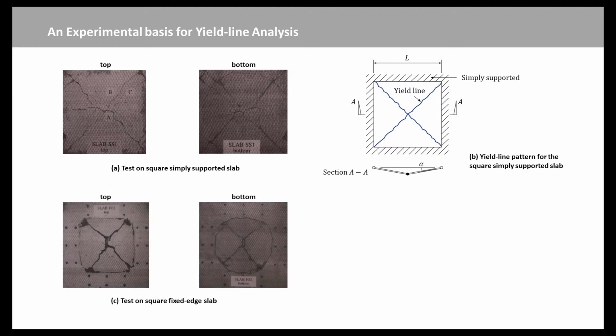Figure C shows a model slab with clamped edges, providing complete restraint of the edges against deformation, after it was tested with an ultimate dead load. The loaded part of the slab was the same size as the simply supported slab. It was necessary to make the specimen larger, with two lines of bolt holes along each side, to create the clamped edges.